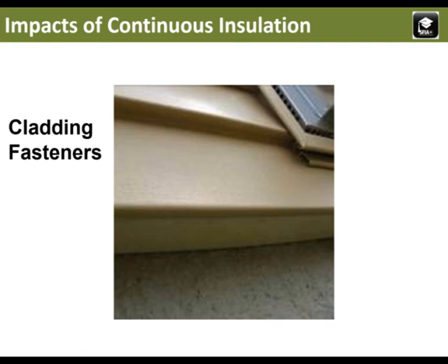But the code doesn't cover all types of cladding or stud configurations, so some assemblies will require an engineered design. If you look at the bottom of the wall in this picture, you see another area where some detailing is needed to cover the exposed foam. Metal flashing is one of the typical solutions.